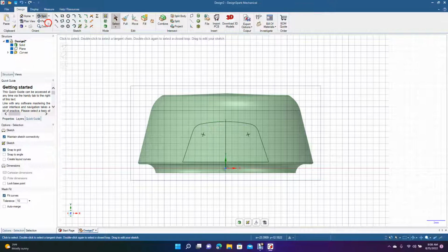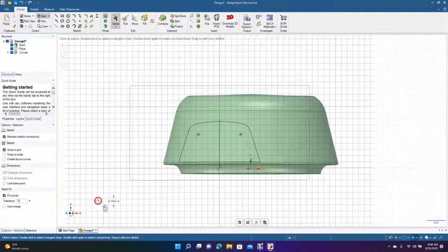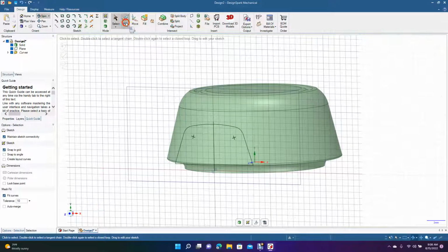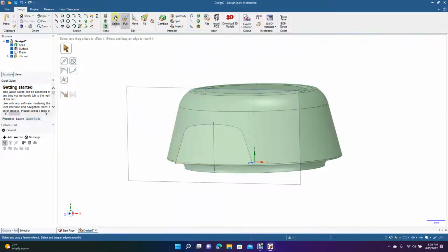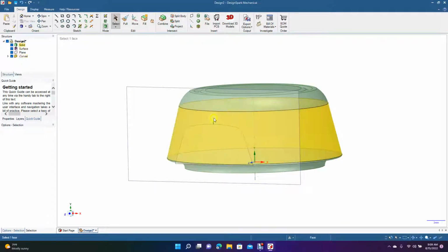All right, so we'll go ahead and spin this. Click on spin. Get that a little bit of a spin. Now we're going to go to pull. Let's get rid of these lines. You don't want to have lines because they'll divide your geometry into two pieces when maybe you only want one. There's a little piece there, but I'm not going to worry about that right now.